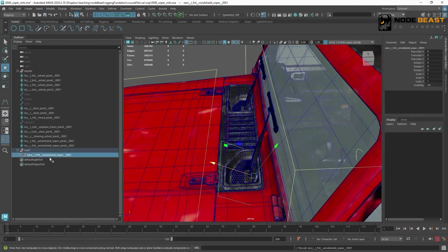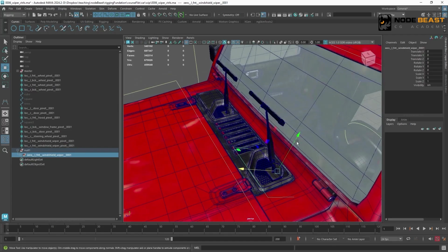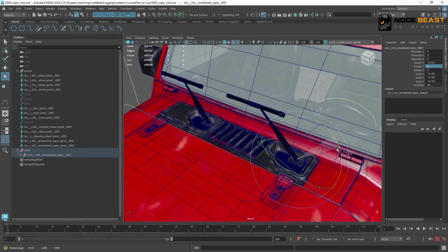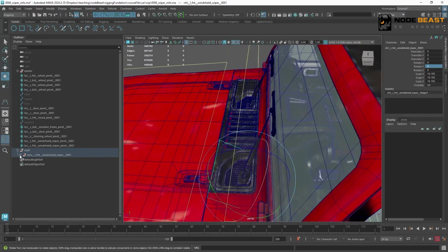Now we'll see the 0 group's translate, rotate, and scale have all returned to default. Now it's very easy to rotate it 180 degrees. For example, I'll rotate the y-axis 180 degrees. Now look, when I rotate the controller again, it's become a positive value. Okay, so this way, we'll select the 0 group again. Press Shift plus P to unparent it from the group we just created.